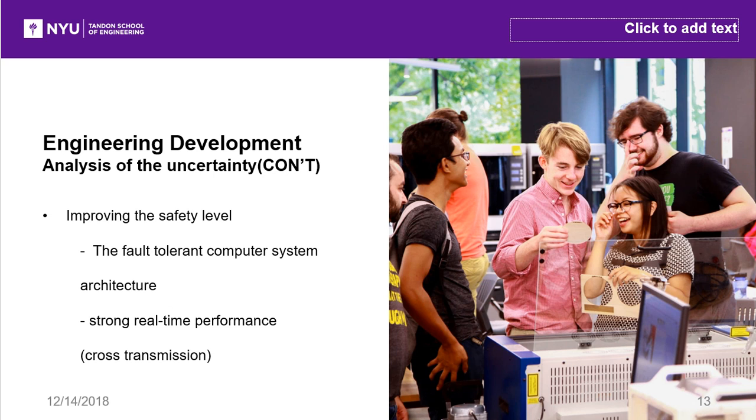Also, the fault-tolerant computer system architecture on the fine-grained configurable aircraft management computer is distributed primarily because of the use of the factory replacement model in the general onboard computer module used. The 3-node computers form a system, and the node computers are connected to each other by a high-speed serial bus.